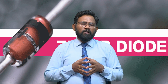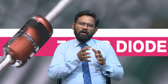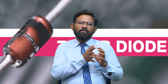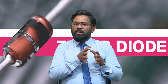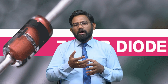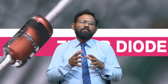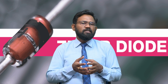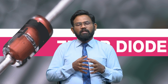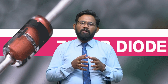It means that when the reverse voltage has not been raised up to Vz, it will remain in the off state. So, to make the Zener diode work in the reverse bias direction, the reverse voltage should cross the value of Vz, and if the voltage remains between 0 and Vz, the Zener diode will remain in the off state, or we can say that the Zener diode does not conduct.